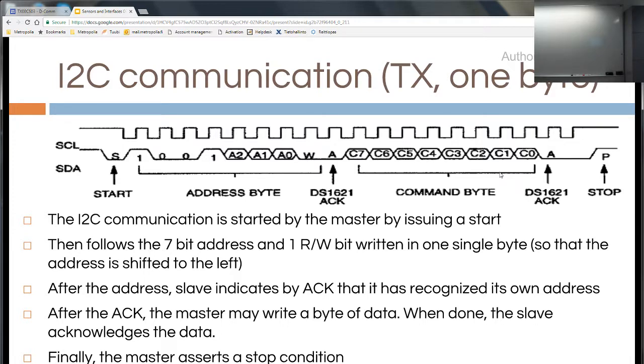Okay, that was the start. Next is the address. 7-bit address. Most significant bit first, 7-bit address transferred so that you have stable data, and then you go with the clock up and down, stable data, clock up and down, and so on.